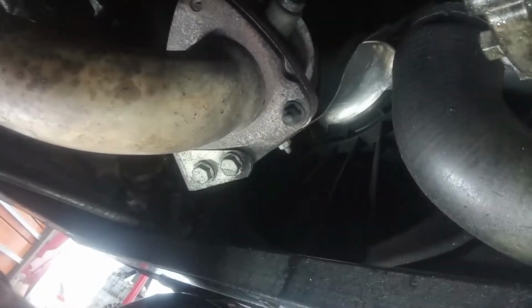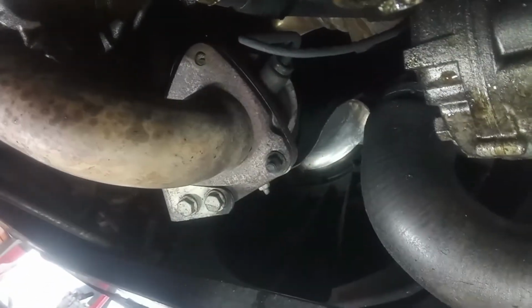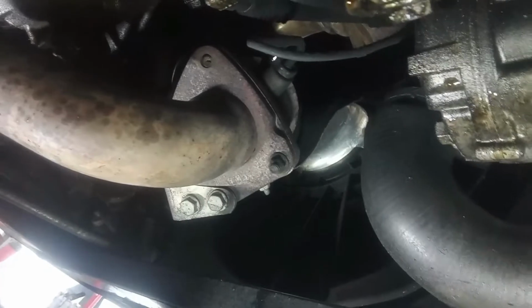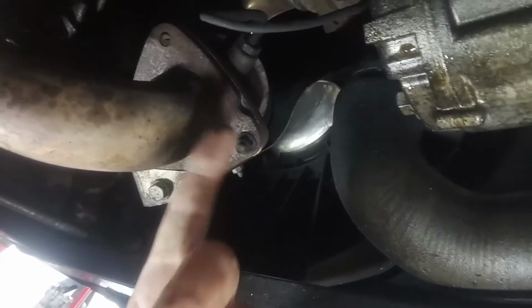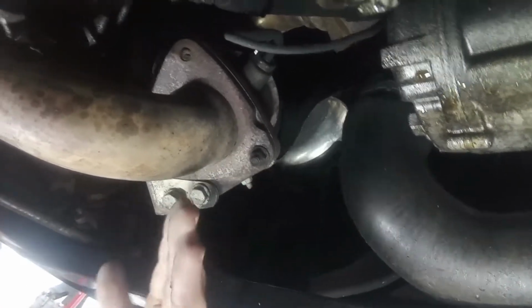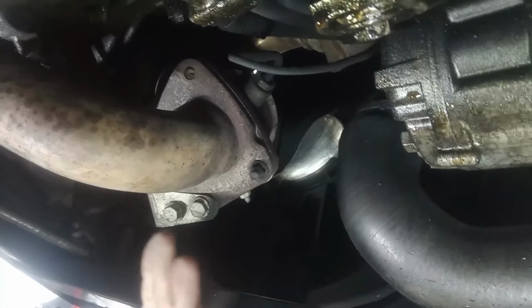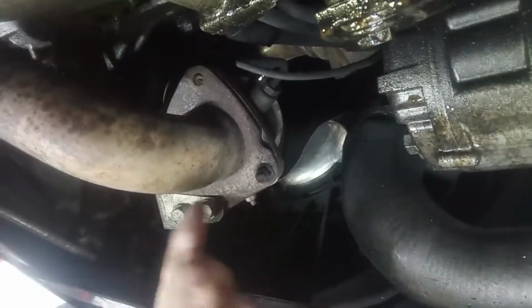Down here on the car, as we are here checking the air filter, that mess, I'm checking here the exhaust. I have a very large exhaust leak over there. That stud is broken. I have to replace it and see if I can fix this leak. What is the problem with that? Remember that you have a sensor, a back pressure sensor on your exhaust because of the DPF. This leak is before that.